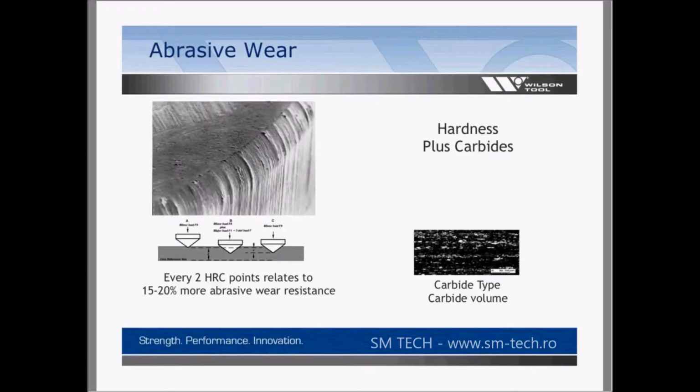Depending on the application, you're looking at abrasive wear itself. That occurs when a hard surface slides across a softer surface. Basically, ASTM defines that as a loss of material due to hard particles that are forced along a solid surface. Obviously, you guys know what that means. It's just your chip wearing away from your work material.